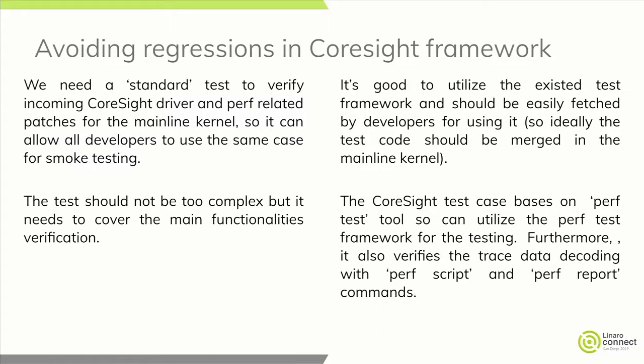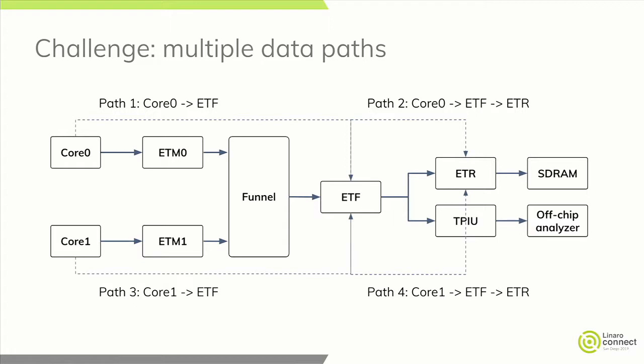Another thing is that using Perf, we can also verify the CoreSight tracing data and verify the decoding, these two phases. This is why we use Perf test. There is one challenge: the CoreSight topology is somewhat complex.